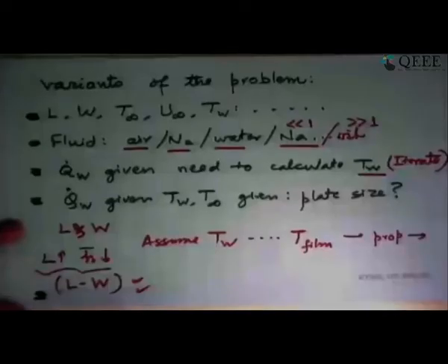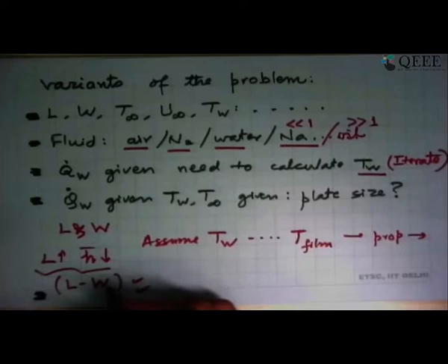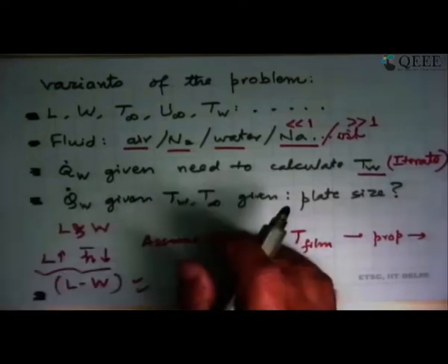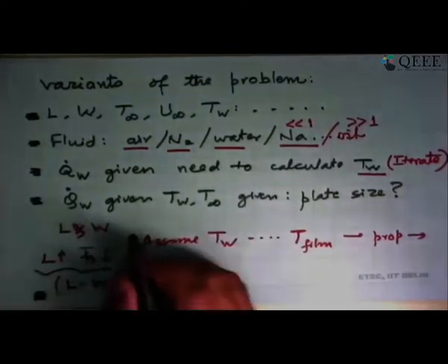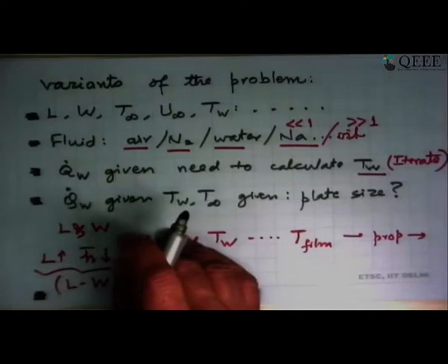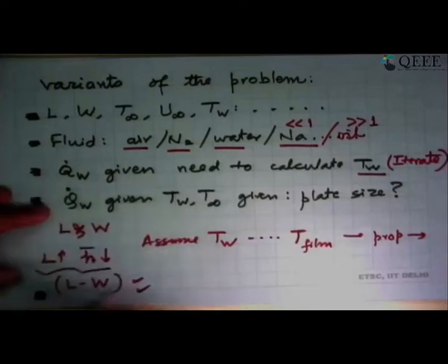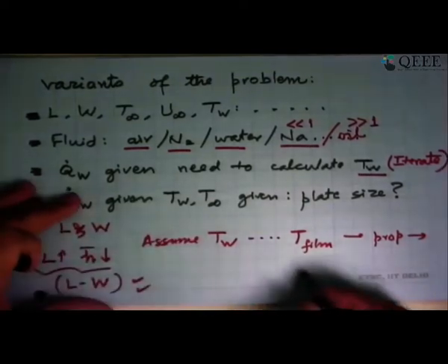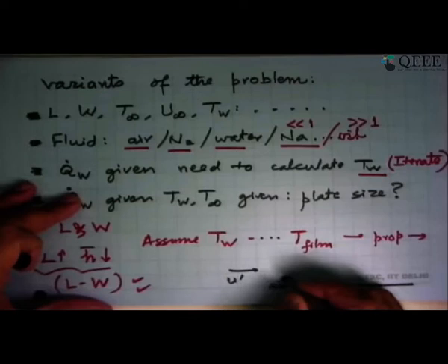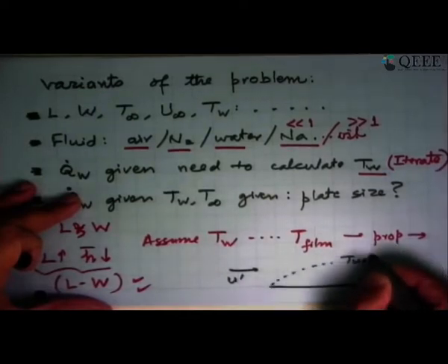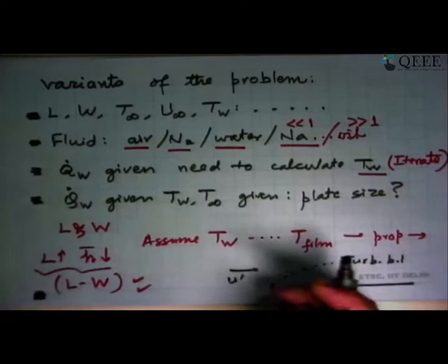Another variable that is worth mentioning is that we assume that the flow of fluid coming onto the plate is laminar. It has no turbulence. In reality, that may not be the case, whether it is the bus or the building that we saw, the air that is flowing around us has some turbulence. If that is the case, the problem takes a very different flavor, because if the free stream has some turbulence in it, some variability u prime, then the boundary layer right from the beginning will grow as a turbulent boundary layer, and there will be no laminar boundary layer at all.